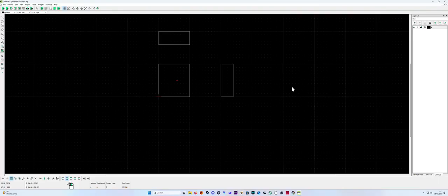a center line. So you go to the layer list here on the right. You see the plus and the minus, and some other things. If you click this one on the right, you open that one. Here you can change the line thickness again. So if you do it wrong and you see later on that you did it wrong, then all the lines that you draw with your 0, just my drawing line, will change to the new settings. But I keep it on 0.5.